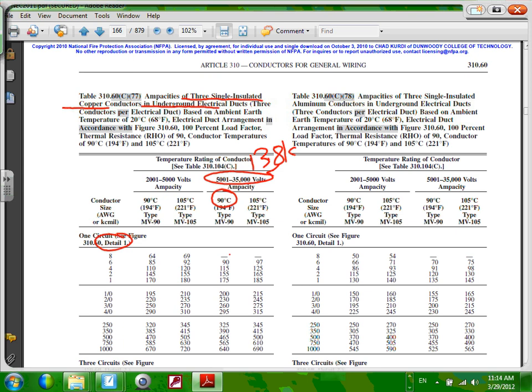So go down all the way. The smallest amp you can start counting is 90. That will cross-reference this baby with which number? Number 6. Any question? Now, on the test, William, if I give you the system is 4160, which set of columns are going to be defaulted to? Right here. So really, most of the time, you are either in this column or that column.